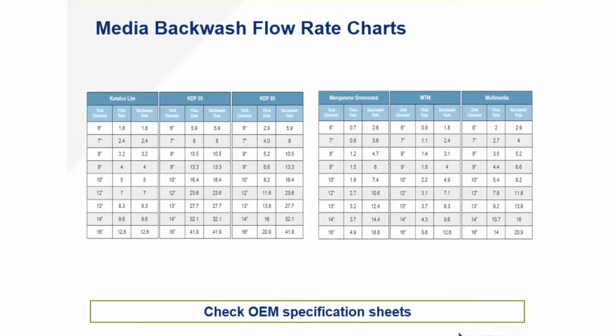So you've got a ton of chemistry going on in that first layer of zeolite or birm inside a bed. Because of the pore structure of zeolites, you may get some lattice structures that form through them and hold the grains together. But that zeolite also gives you the fine particulate filtration you may want. Depending on water chemistry, if it's locking up on you,